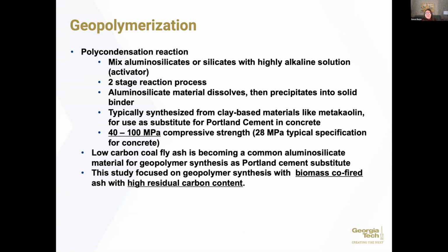In addition to bricks, we've also done some work looking at geopolymerization. So this is a condensation reaction. Essentially, we take an aluminosilicate material, we mix it with an alkaline solution, and we come through with a 2-stage reaction process. So we dissolve it, and then we precipitate it into a solid binder.